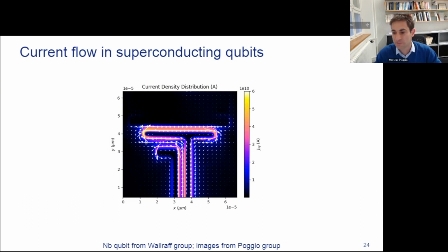Right, very good. Yes, so in fact, the bandwidth of the SQUID device itself is very, very high. You should be able to go maybe up to gigahertz or so. But with all the amplifiers and things that we have, we're limited to the tens of kilohertz, maybe 100 kilohertz or so. And so, yes, we can't pick up the very, very high frequencies that are involved in the actual running of the qubits. So we do these experiments at quite a bit lower frequencies. In principle, you could imagine doing the imaging at these higher frequencies if you redesign the scanning probe system, but it would involve quite some effort. And for now, we've concentrated on what happens at lower frequencies.